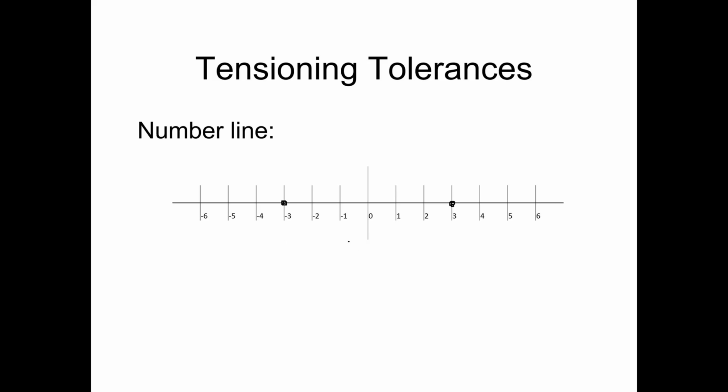All right, let's do another example. Next strand, same tensioning operation. We're being consistent with our force, and so we are applying a force that's 3% over the required force, so that value is still good. We measure our elongation, and the elongation for our second strand is 2% over the calculated elongation.